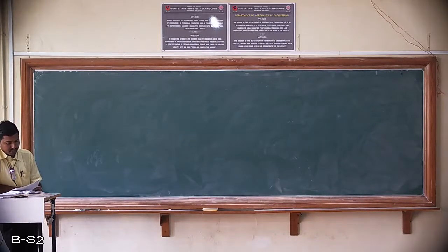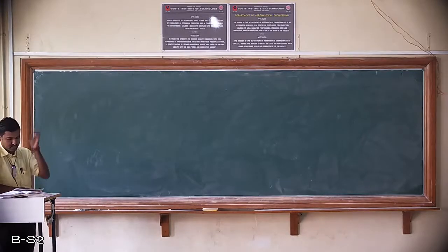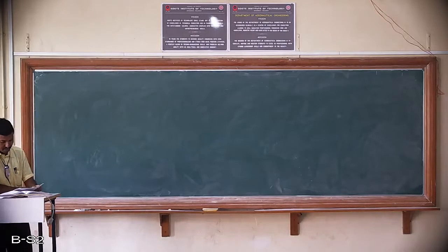The minimum equilibrium speed is 420 rpm and maximum equilibrium speed is 4% higher than this. Neglecting the obliquity of arms, determine first the spring stiffness, second the initial compression, and third the equilibrium speed corresponding to the radius of rotation of 95 mm.